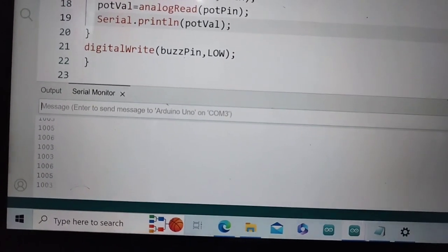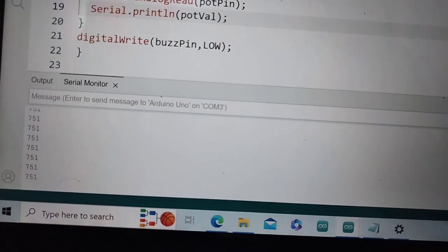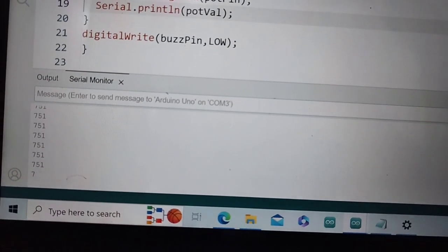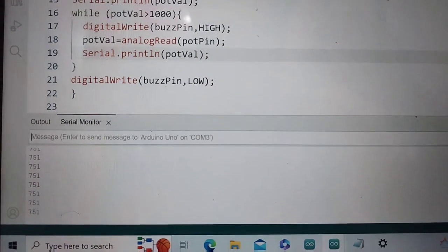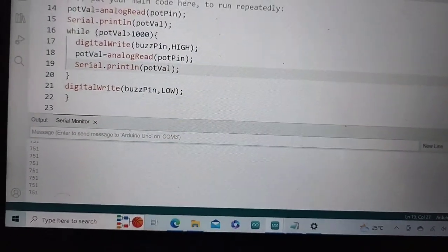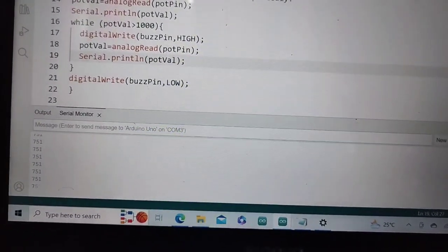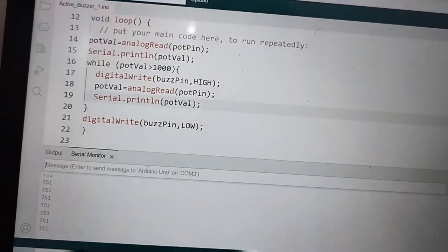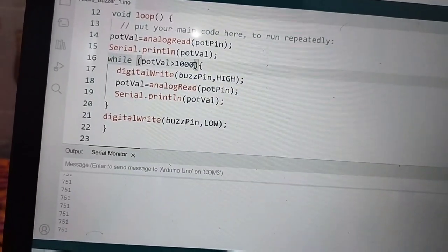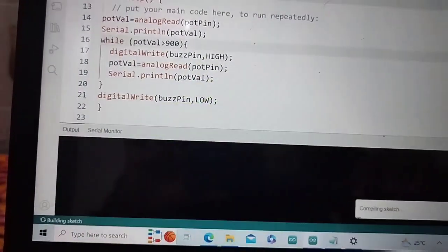and this small disturbance that we heard is caused because the value keeps fluctuating between 999 and 1000. Since our hands are not capable of maintaining the exact value, that fluctuation takes place at that one point. But once it crosses 1000 and touches 1023, the buzzer keeps buzzing without any disturbance. So I'll just change the value here to above 900, and let's just download the code.